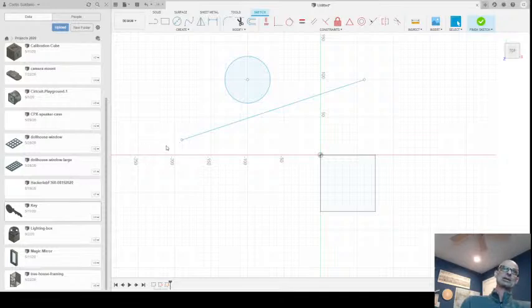You know that's going to go back to here, and pass up and continue on and on and on. So when we set a tangential constraint, it can be anything along that ray. It doesn't have to just be along the line that I have highlighted here. So you can see the tangent is demonstrating the concept visually. It constrains a curve and another object so they touch at a single point but never cross each other. Maybe I didn't highlight the never cross each other aspect of it, but this edge of this circle will ride anywhere on this line.